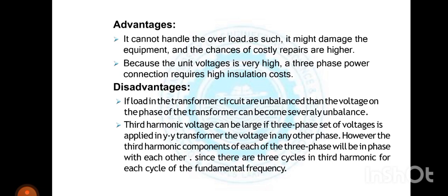Disadvantages: if loads in the transformer circuit are unbalanced, then the voltage on the phases of the transformer can become severely unbalanced. Third, harmonic voltage can be large if a three-phase set of voltages is applied to a YY transformer.